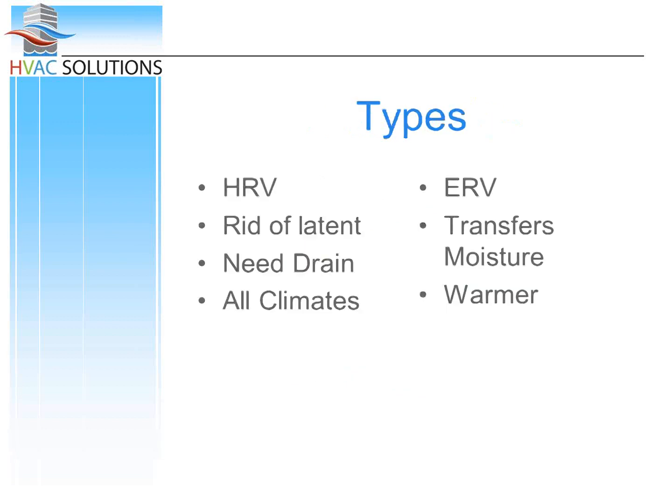I'm going to tell you no. It's more like 65 degrees and 60% relative humidity plus. So portable units don't work real well. They've got a really hard time getting to dew point. And that's where whole house dehumidifiers make a lot of sense for wet basements.